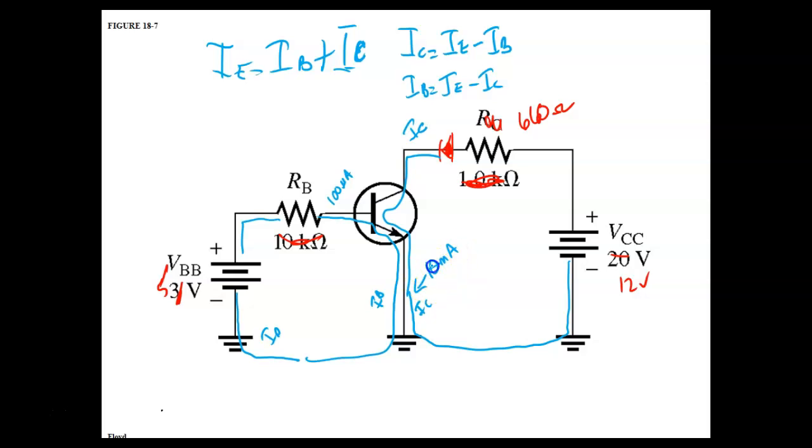Over here, we might have had 10.1 milliamps. So for all practical purposes, 10.1 milliamps on the emitter, 10 milliamps on the collector. So what we do in formulas is we just assume they're the same, because there's not going to be enough difference to affect our math, right? You understand why? Yes or no?